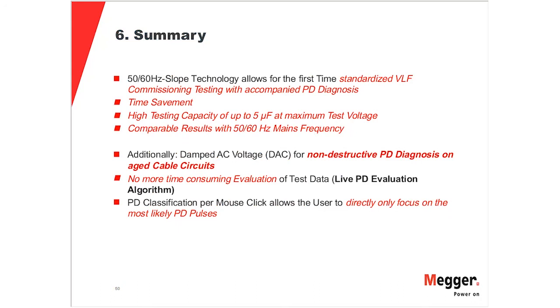Again, I'm not saying VLF sinusoidal is bad, because we are using it ourselves, but we are only using it for tangent delta, because we found out that the results achieved are not reflecting the reality and are therefore kind of useless. Now, what is the summary? I believe my time is slowly running out.